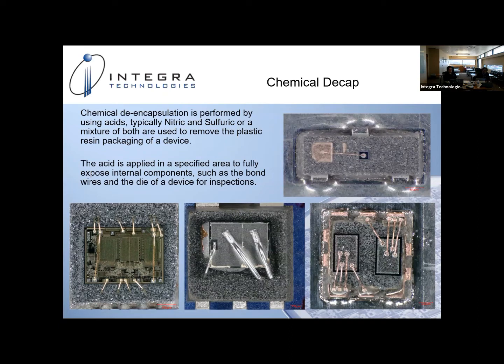But in order to be a little bit safer, or quite a bit safer, you really want to do laser ablation. Before laser ablation, there was nothing but the manual chemical decap anyway, for years and years and years. And we did it. Everybody else did it. So, can it be done? Yes, it can be done. Is it easy? No. You really got to fine tune that process. Cleaning it up, getting what you need, that's the fine tuning of it. But laser ablation helps you greatly with that process.